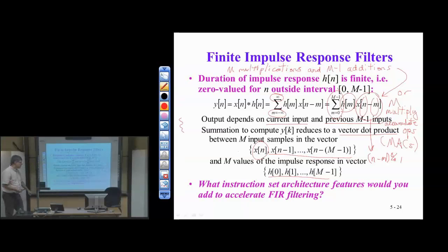Again, just to summarize here, I also need fast on-chip memory to be able to get the data. So x is stored in on-chip memory, local memory. I need to get that to the registers fast. I also need to read in the coefficient values, h[0], h[1], and so forth, fast. So if I put that all together, what do I need? A fast down counter. I need fast multiplication, fast addition. I need fast local memory and a fast local bus.